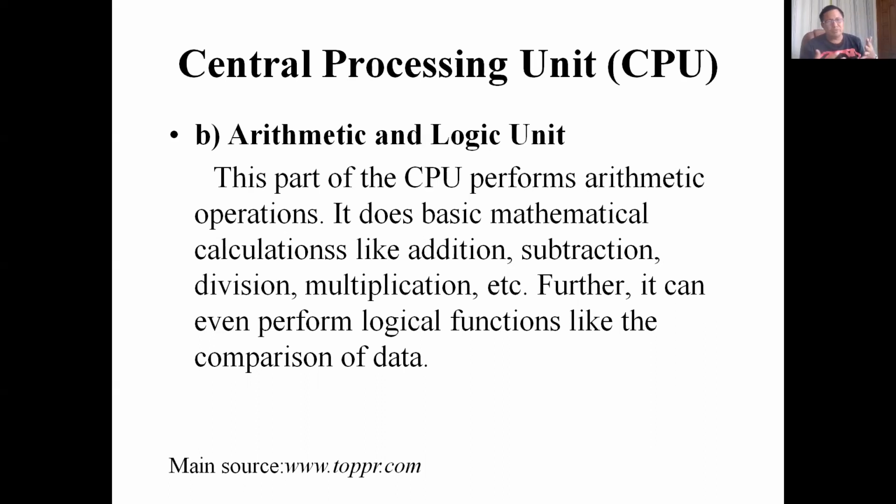You can connect two nibbles together in series. The last carry is connected to the next carry and it becomes bigger. The technique is called bit slicing, adding two nibbles or two bytes together to be able to perform bigger addition or subtraction. So that's called the arithmetic logic unit. I've shown you the circuit already, right?